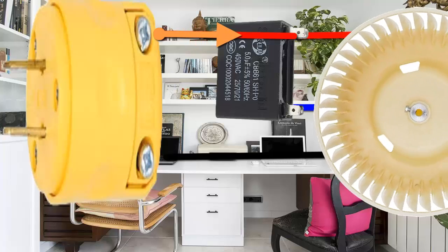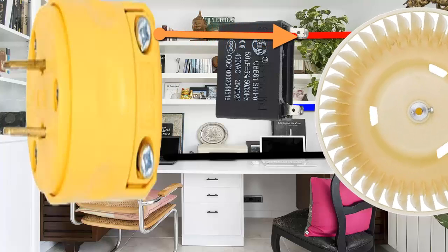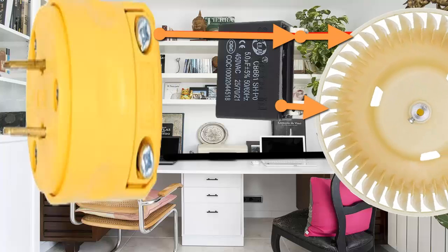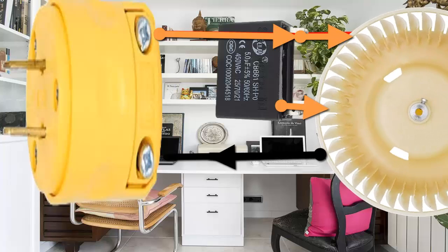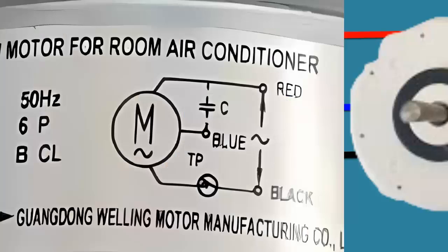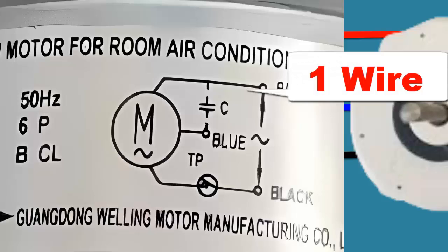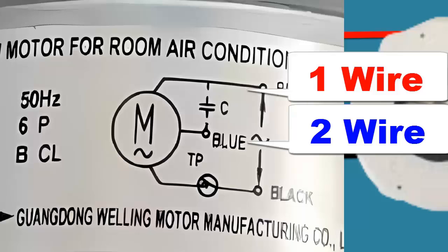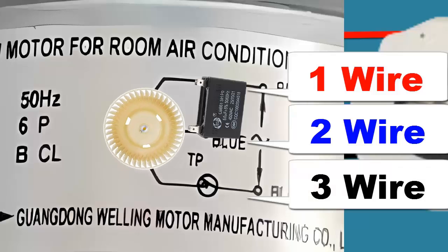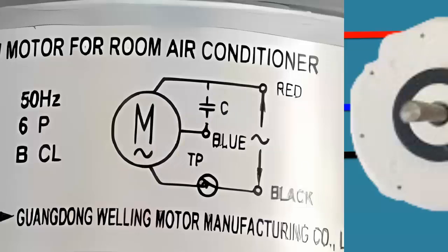In this video, we will explore the connection and main characteristics of single-speed fan motors used in single-phase air conditioners. On the screen, the diagram of a 3-wire motor is presented. 1. The 3-wire motor is a single-speed motor, whose operation is controlled by a relay located on the electronic board.